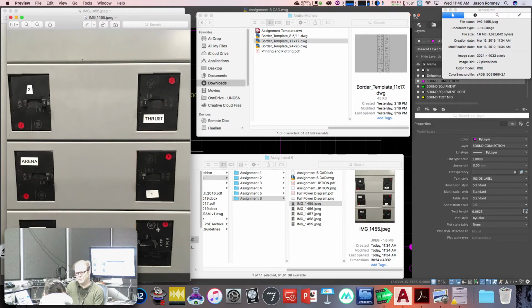It's theoretically possible to trip that breaker, even if I don't trip these. But in reality, it's probably a 3-phase breaker, which means I probably have 400 amps 3 times. And depending on how these things are wired up, it would have to be for these to be three phase. But for the purpose of a one-line power diagram, the whole point of that diagram is you really don't pay a whole lot of attention to phase, because it gets a little dicey.